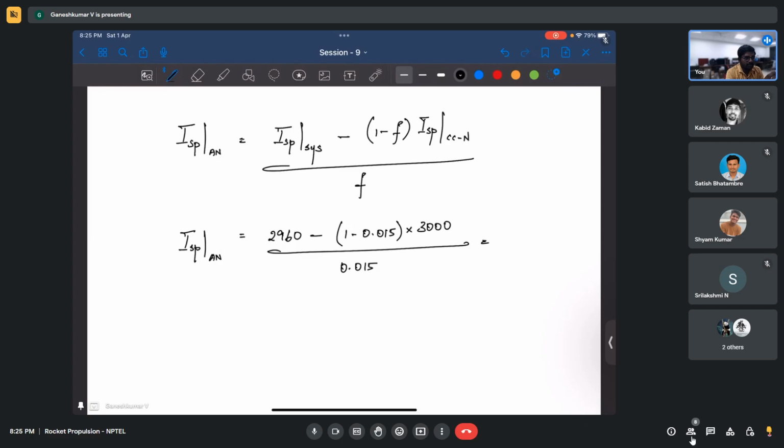So this is like a compounding effect. If you would have given that mass flow rate to the main combustion chamber, you are going to get higher specific impulse, but you divided it and gave it to a less efficient system. So overall specific impulse should come down, right? In that way.